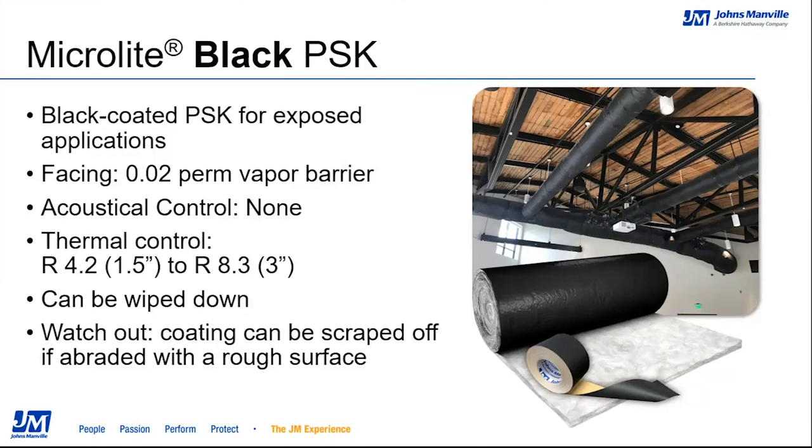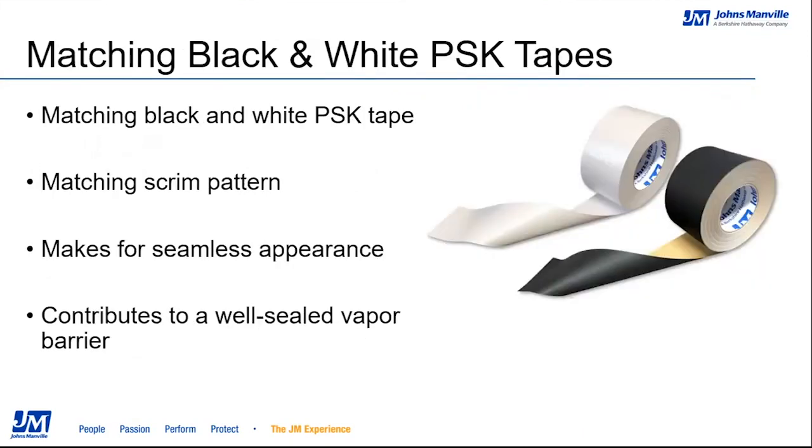And lastly, the key benefit of this product, and Brennan hit this a little bit earlier, is that it does not have to be painted after installation, which helps alleviate additional cost and headache and heartache to a contractor and to an end user for that matter. In addition, painting duct wrap voids your UL 2550 flame and smoke warranty. And Johns Manville, there are so many paints out on the marketplace. When we go and test to get ASTM E84 approval, we test as it is in its original state from our manufacturing facility. So for all the paints that are out there, we do not advise painting duct wrap.